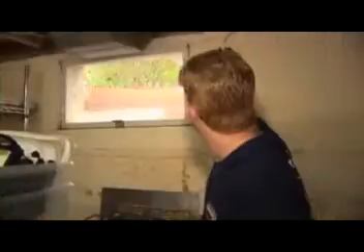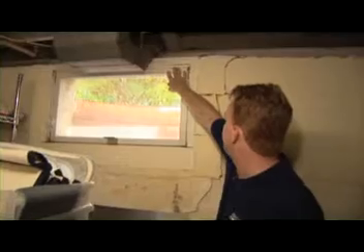With the blower door fan still pulling air out of the house, Larry tests the basement. It's not a bad number. While the basement's not a conditioned space, we don't want to see a lot of air infiltration in a basement. So you want to seal all the holes and penetrations in the basement that allow air from the outside to come in. Now he looks for the source of those air leaks.